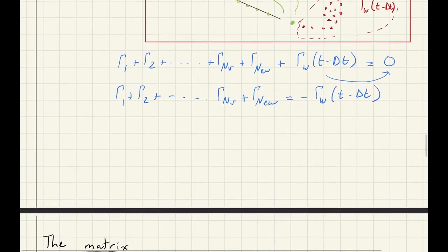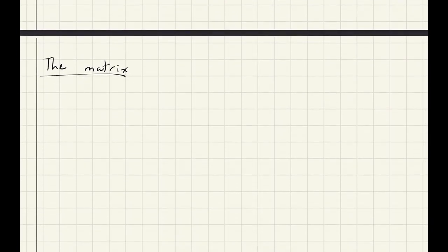All right, moving on, we can form the matrix. We start off exactly as we did last time. Remember the influence coefficients. We have A1,1, A1,2, A1,3, where the first index is the collocation point and the second index is the bound vortex. So it goes until A1,NV, and then we go down. Now we're varying the collocation point when we switch from one row to the next.